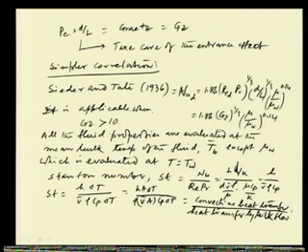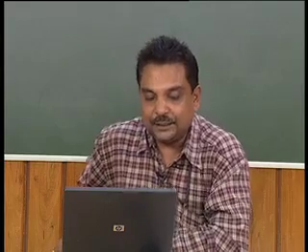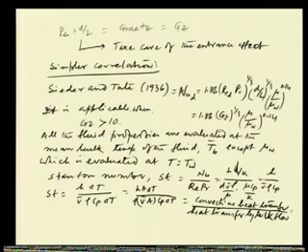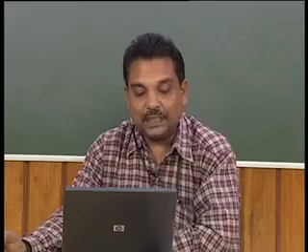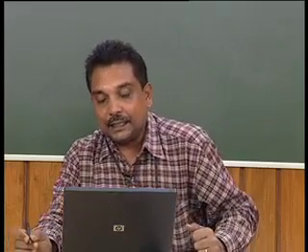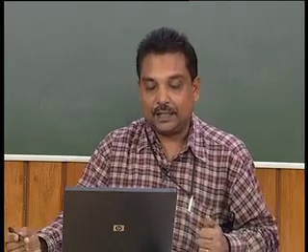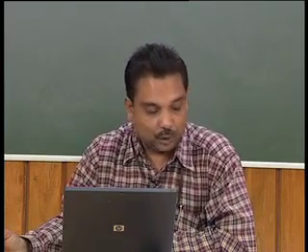Now, here it is the Stanton number, and previously we discussed the Peclet number. In case of Peclet number, we saw it is heat transfer by bulk flow divided by heat transfer by thermal diffusion or conductive heat transfer. But the Stanton number says it is convective heat transfer divided by heat transfer by bulk flow. So, we have a relationship between bulk flow heat transfer and convective or conductive heat transfer, either by the Peclet number or by the Stanton number.